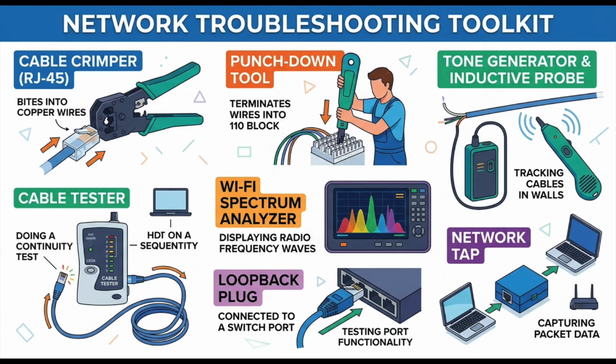What if they light up out of order? If the lights illuminate out of order, say, the tester sends on pin 2 but receives on pin 3, you accidentally crossed your color-coded wires inside the RJ45 connector. Let me pose a scenario based on an analogy. Sure. Say a continuity tester gives you all green lights, 1 through 8. Everything cycles perfectly. Some people might assume that guarantees a flawless high-speed network connection. But isn't a continuity tester just checking if the plumbing pipes are connected?